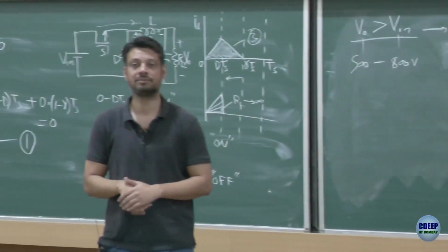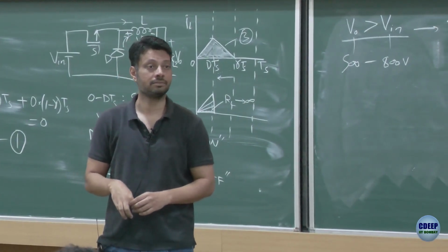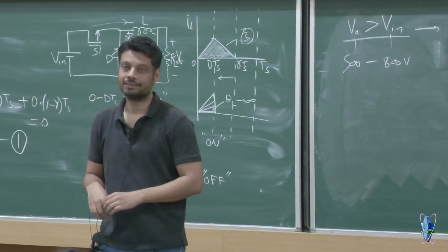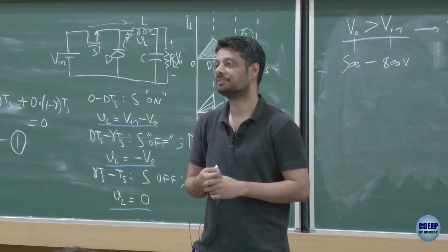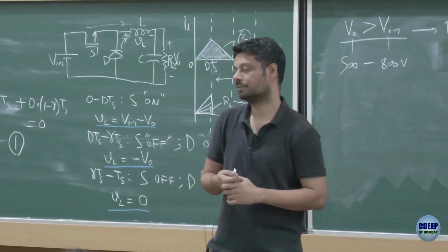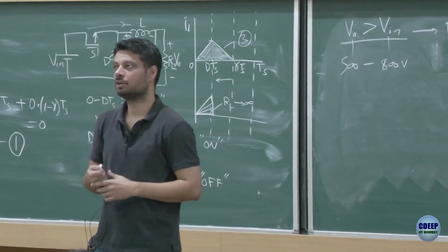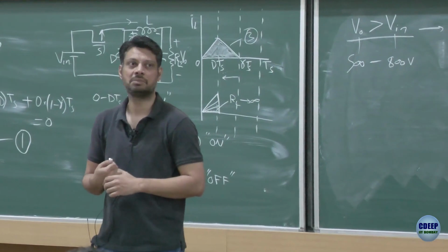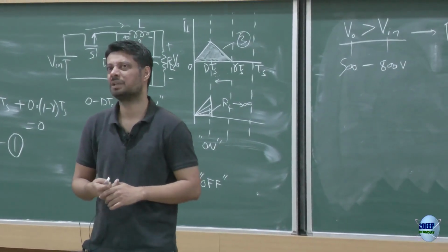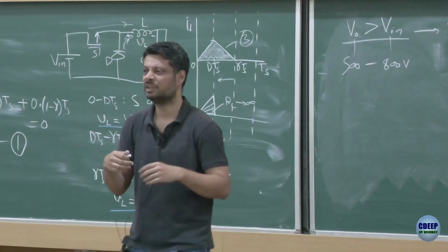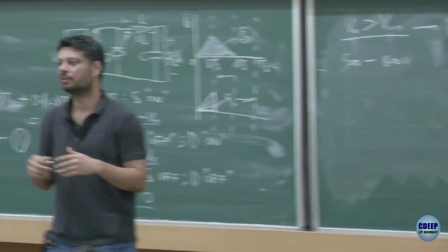Any other application? What would you do in a data center? Okay, not like that, think a bit. Yeah, so what he's saying is high voltage DC transmission. You don't usually use boost there because you want to increase the voltage by a very, very large amount. We'll see later on that boost is not really capable of very large boost.